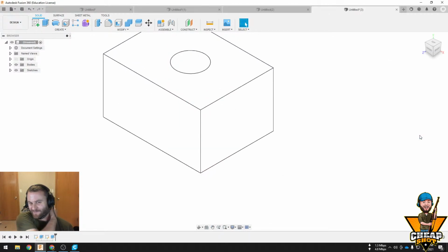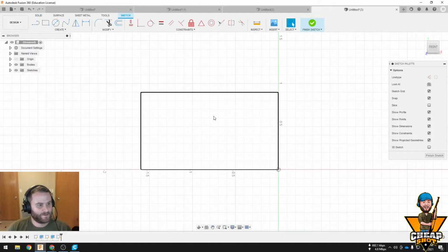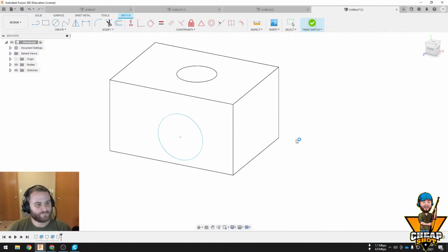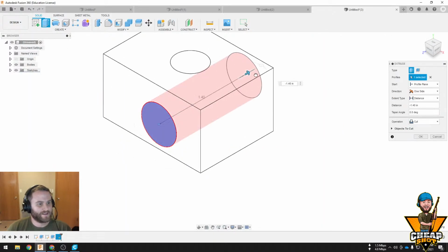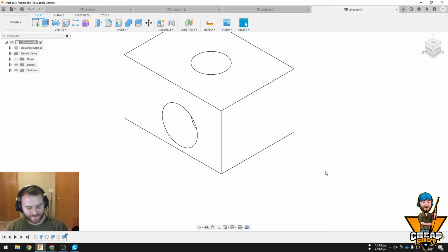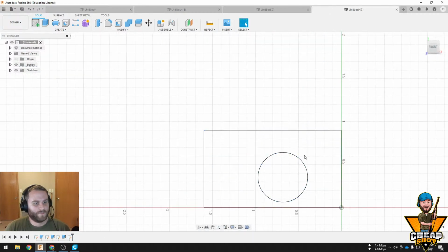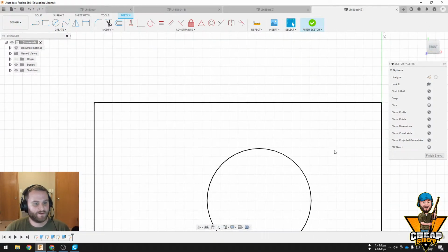Depending on how accurate my machine is, it's going to print it no problem. It might ooze a little bit and make it smaller than what I think it is, but it'll still work fine. Printers hate printing in this direction, and the reason is because we're using flatness to make a circle.